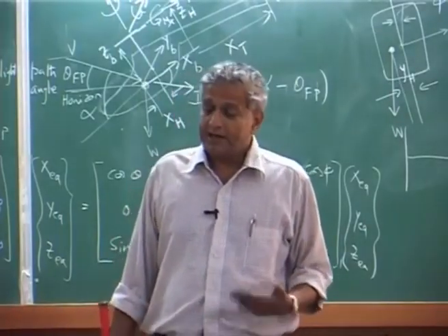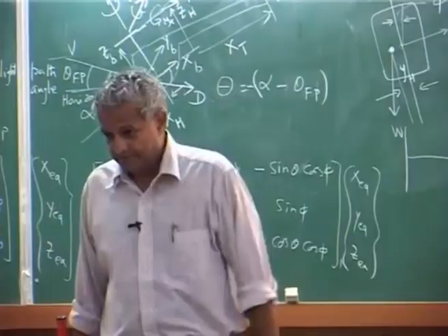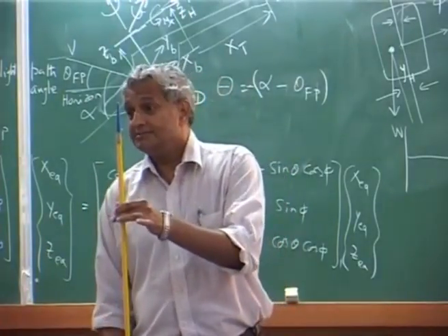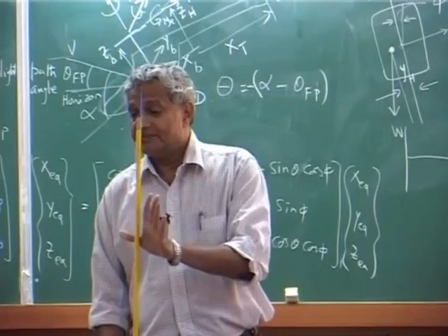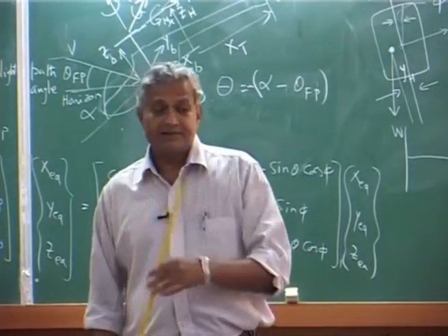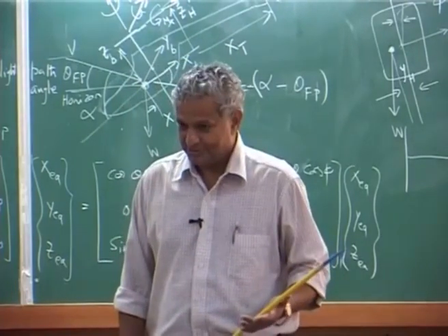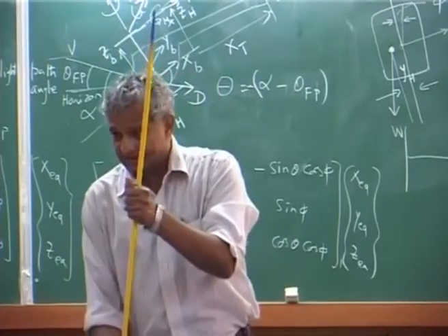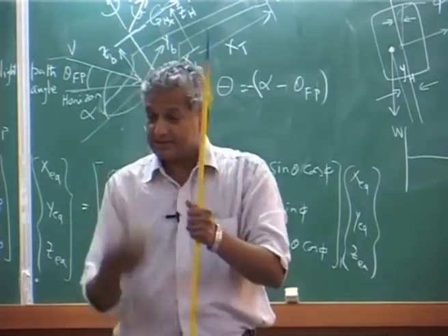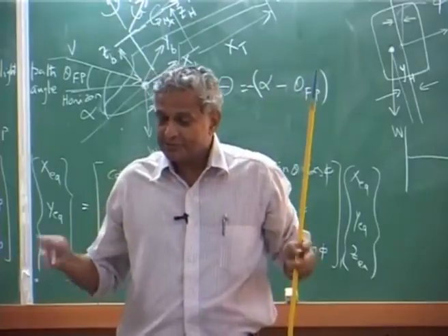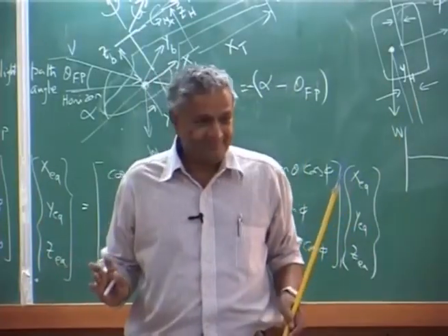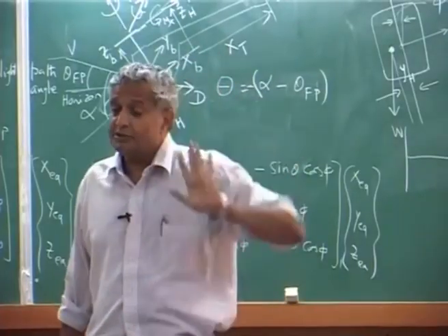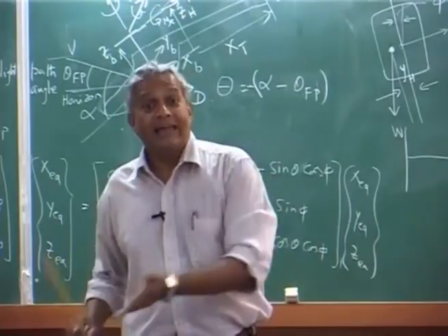Now, another aspect is you can do a wind tunnel test. In a wind tunnel, what happens is it is kept at a specific shaft angle. That means alpha is fixed. That is called a wind tunnel trim. There you do not go and balance the thrust, because it is held. Whatever force comes, it is not that it is equal to weight. So, the thrust equation is out. You may directly solve for the forces developed only. There is no equilibrium equation.